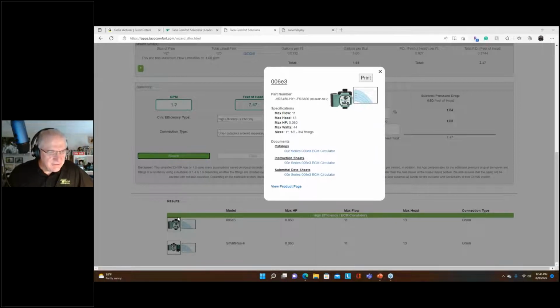Let's see. Steve, yeah, okay, got that, Steve. On the recirc system using the hotlink crossover valves, would the ECM circulator still be set to minimum? Good question, Travis. It would be set to where it needs to be for that system. Remember, it's not cumulative. Think of those hotlink valves as zone valves. Whatever the flow rate you need is the flow rate you need. So yeah, you would still set it to minimum, but they're like zone valves, right? It's not cumulative head, it's in parallel. So if you think of them like that, hopefully that'll make sense. But you still need to respect the gallons per minute limitation with hotlink valves, which we're going to look at in just a second.